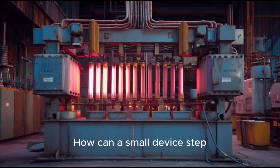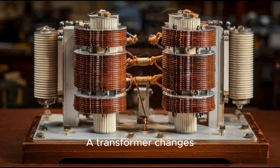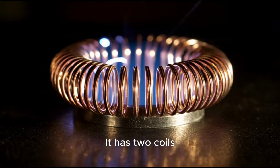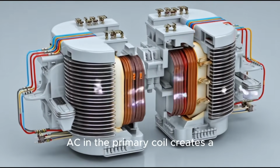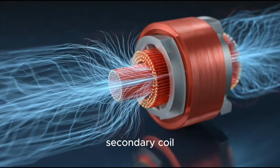How can a small device step 11,000 volts down to 230 volts? A transformer changes AC voltage levels using magnetic induction. It has two coils, primary and secondary. AC in the primary coil creates a changing magnetic field. This induces voltage in the secondary coil.